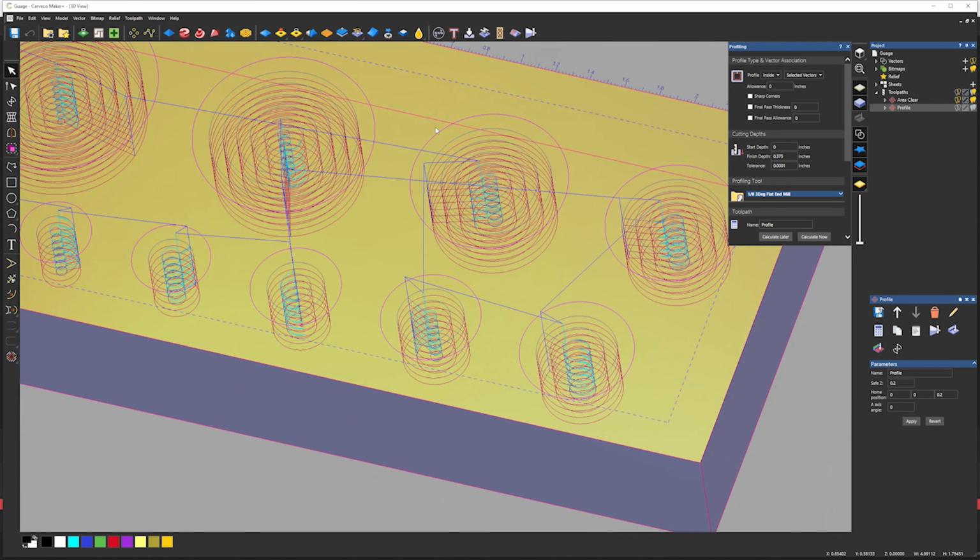Next thing we're going to set up is the profile. This profile will only go around the diameter on the inside. This is just to clean up that extra 10 thousandths we left, and then it'll give us a nice clean cut in a perfect circle when we're done. So we're doing the same depth, 375, and the same tool, 1/8 inch, 3-degree flat. We use a 3-degree for the relief so that when you put glass or metal into a mold, it comes out really easily. But it's so small you don't really see the angle on it.